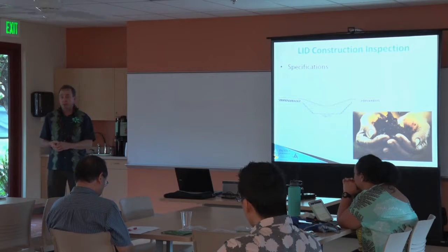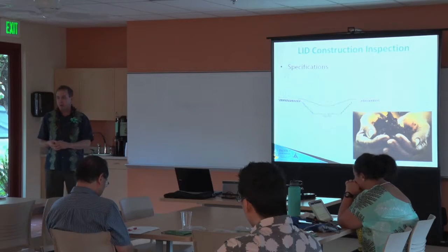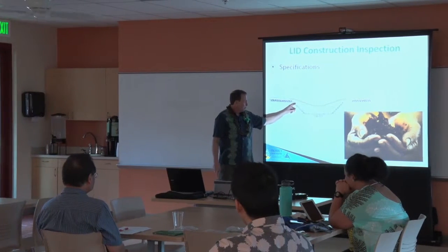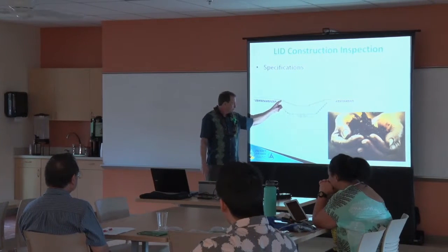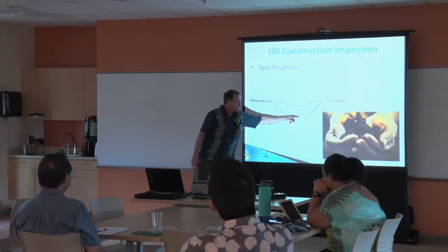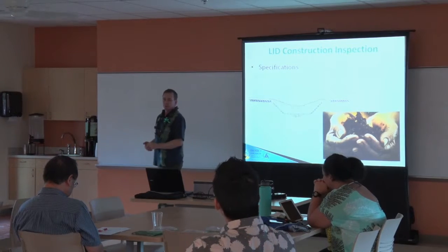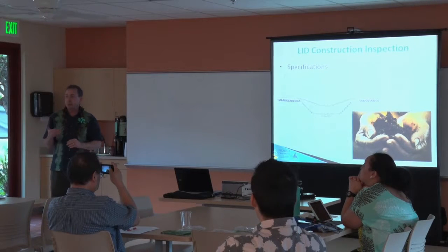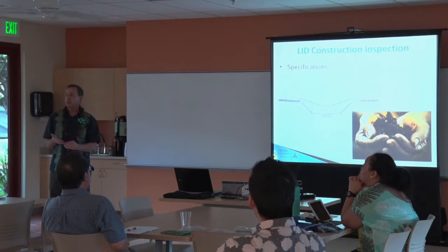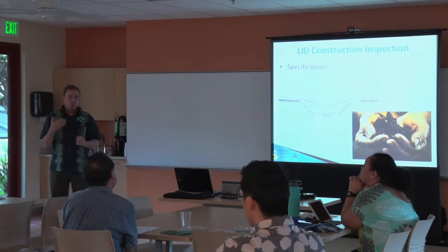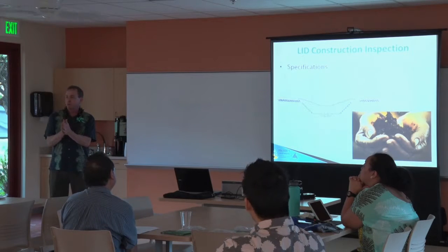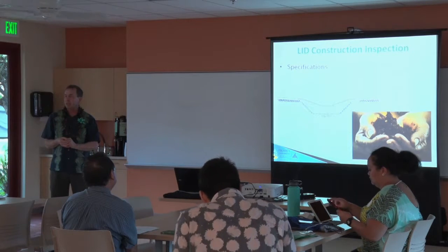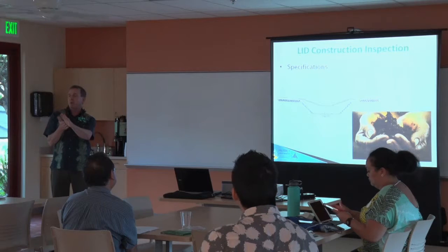Another common feature, and I try and avoid this and push designers to avoid it, but we often see a layer of filter fabric between here, or not on the surface so much, or they'll wrap this in a filter fabric material. And again, we need to make sure, one, that we're specifying the right type of material, something that's permeable and is going to let the water through. But what can happen with some of these tighter woven geotextiles, you get one dose of fine sediment in there and it will just coat that fabric and blind it.